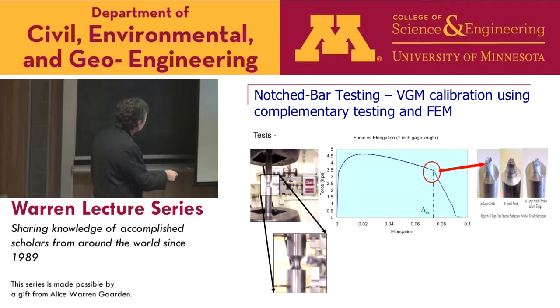And then when you look inside of this surface here, the question is what's happening to that surface, what's driving the fracture. So we need to look inside to characterize the stresses and strains at that fracture location. Sometimes we'll put extensometers on and say strain is equal to delta divided by the gauge length. That's a macroscopic measure of strain. We want to look at the very high strains that are localizing here where the fracture is occurring.